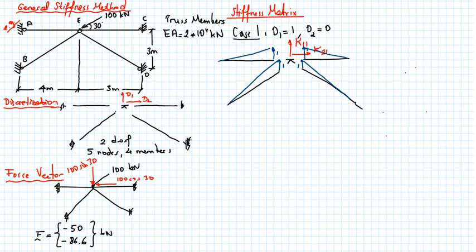Okay. Now, if we take a look at member AE, it moves in the transverse direction. So by definition, if the translation is in the transverse direction, it doesn't cause any shortening or elongation. So this is our main assumption. In order to have a shortening or elongation, the translation or the deformation must be along the element axis.